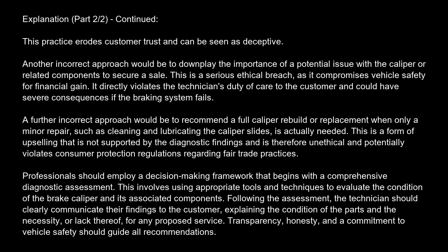fails. A further incorrect approach would be to recommend a full caliper rebuild or replacement when only a minor repair, such as cleaning and lubricating the caliper slides, is actually needed. This is a form of upselling that is not supported by the diagnostic findings and is therefore unethical and potentially violates consumer protection regulations regarding fair trade practices.